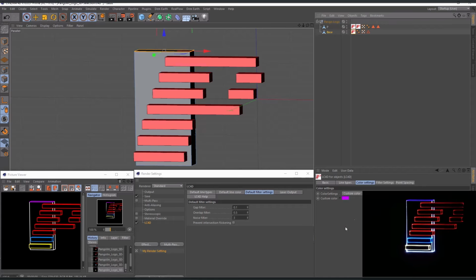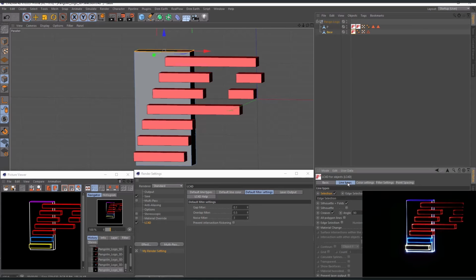Besides all this recoloration stuff, I might also choose another function and, for example, would like to have those 4 selected edges invisible in my rendered frame. This might be really interesting, for example, in very complex frames, where it might be helpful to hide some less important lines in your graphic to reduce the overall number of points your scanners have to run. So let's skip laser output only for those 4 lines. In the laser output video, you can see that those lines are now no longer included, and we saved several points to reduce flickering in our laser graphics.